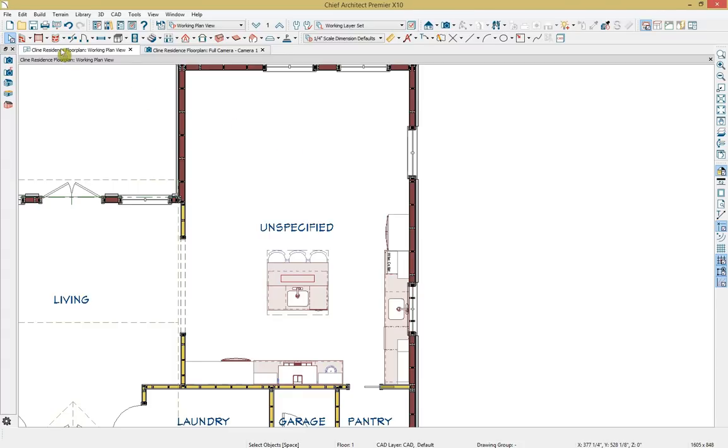And I'm going to do that using a tool called the room divider, which is going to act as a visible wall but without actually placing a wall. So with the room divider tool selected, I'm just going to click and drag where I want to separate these two spaces, and you'll notice how I separated those spaces there.